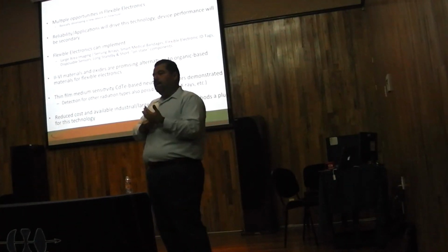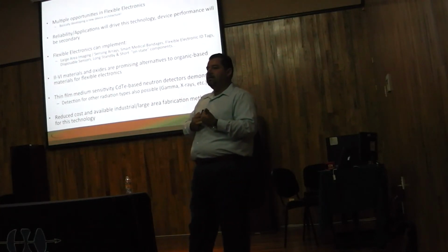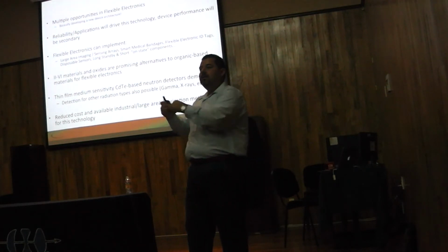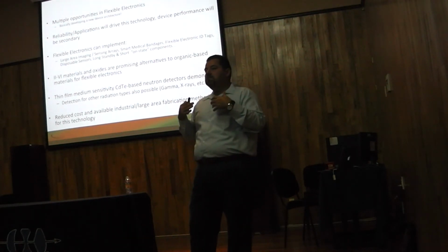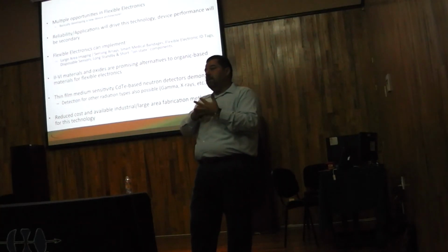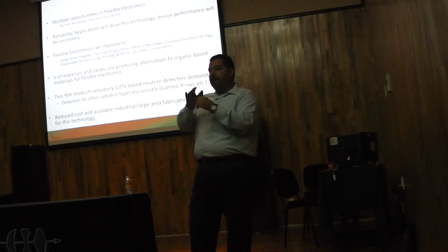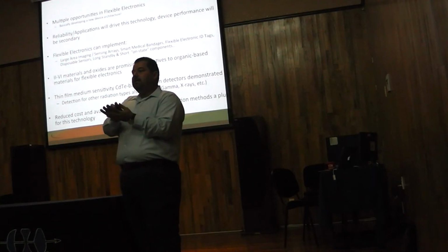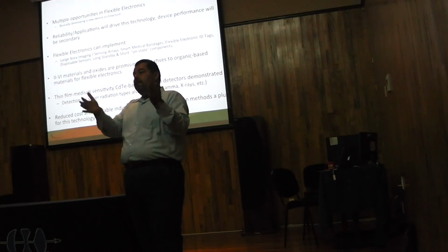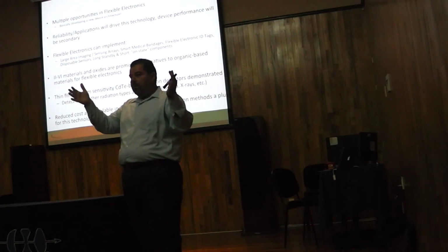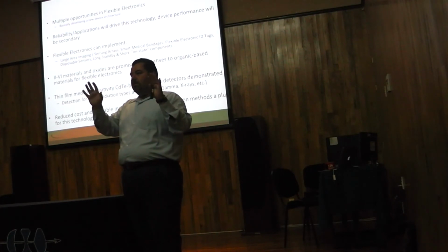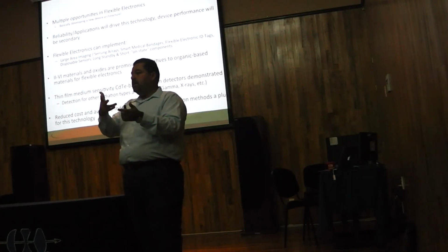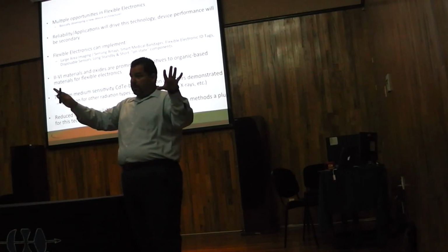Absolutely. I think the limitation for reliability is defined by where the device is going to be used. If it's going to be inside, it may be okay. If it's outside, it will need a much better encapsulation. For organic devices, whenever you finish the device, you need to encapsulate it before you remove it from the ambient where it was built. So you have a glove box with a nice environment, no oxygen, no moisture. You have to encapsulate it there before you take it out, because as soon as you take it out, it's going to start degrading. So it depends a lot on where it's going to be used.